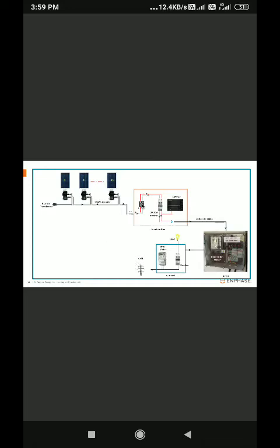This junction box which is inverted is a roof isolator where you have an MCB, a breaker. This is for surge protection. Okay, and you feed the single phase from the grid, from the meter. So the single phase 2 wire will go to this MCB. Okay, and once the grid is given, based on the grid sensors it operates. So this is our simple single line schematic.